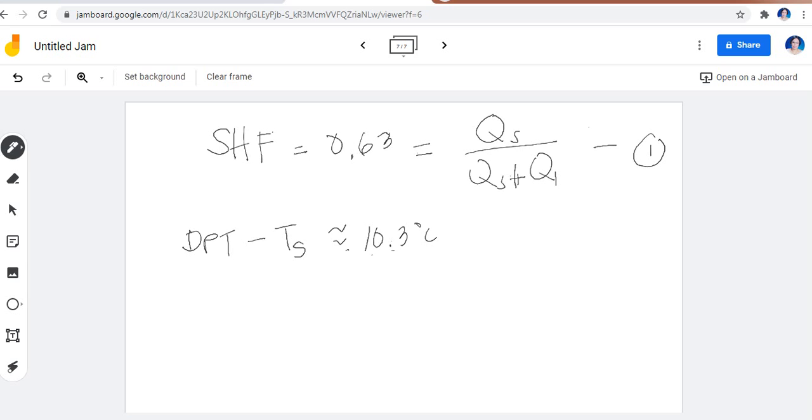The line connecting these two points, you extend until it reaches the 100% saturation line. From that point, which is the extension of the line connecting state 1 and 2 on the 100% relative humidity saturated line, you read the dew point temperature of 10.3 degrees Celsius.